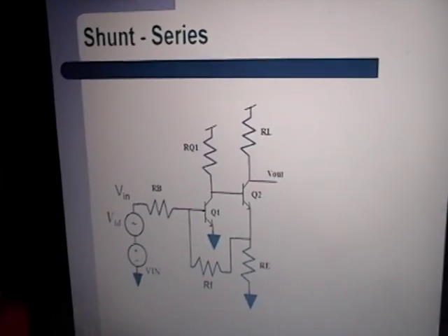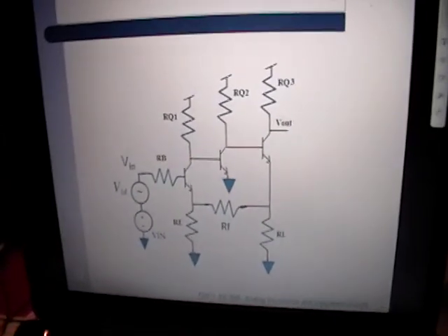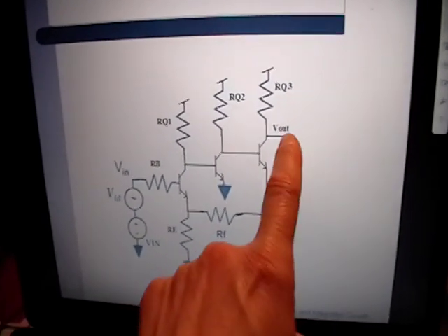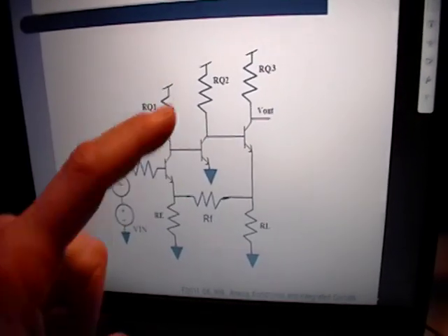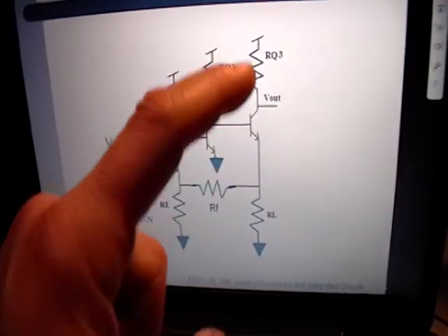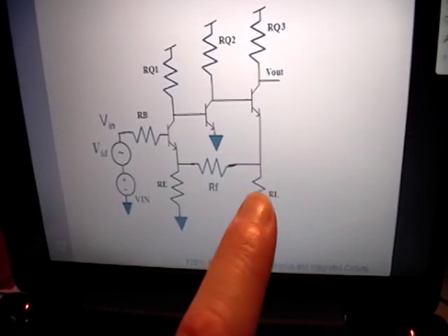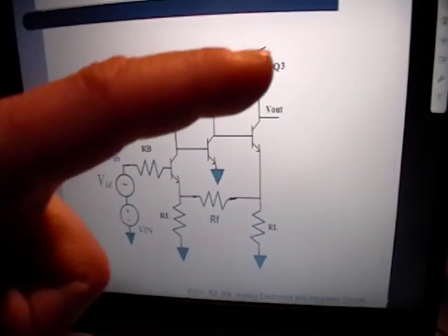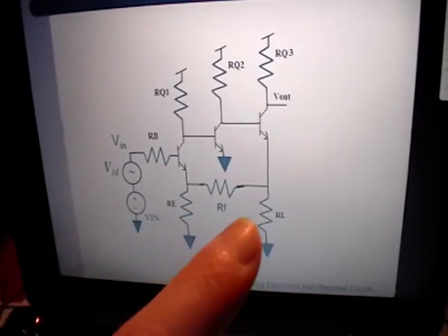Okay, and the final one for practice, and we'll see why these matter, is right here. Let's see, is V out, let's get rid of our vanilla stuff. There's a vanilla, there's a vanilla, and this is still a common emitter, so this is a vanilla here. This is degeneration for this amplifier. So the vanilla amplifier is just this up here. So all of this back here becomes your feedback network.